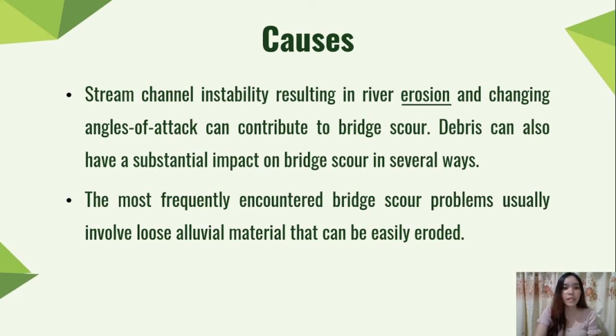And the second point is that the most frequently encountered bridge scour problems usually involve loose alluvial material that can be easily eroded. However, one should not assume that total scour in cohesive or cemented soils will not be as large as in non-cohesive soils. The scour simply takes longer to develop.